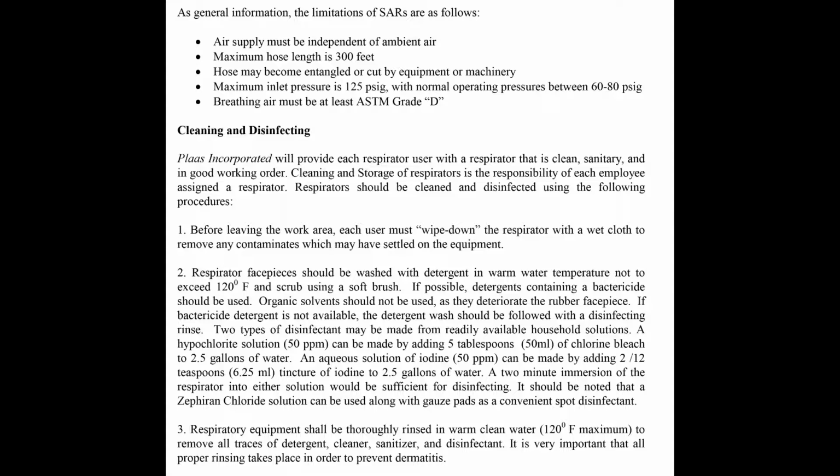Respirator facepiece should be washed with detergent in warm water, temperature not to exceed 120 degrees Fahrenheit, and scrubbed using a soft brush. If possible, detergents containing a bactericide should be used. Organic solvents should not be used as they deteriorate the rubber facepiece. If bactericide detergent is not available, the detergent wash should be followed with a disinfecting rinse.